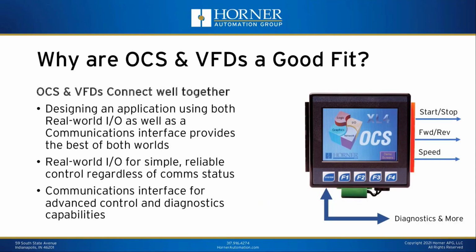So in addition to the I/O connection for basic start, stop, and speed control capability, you've got the ability to add either a full-blown Ethernet or fieldbus-based network connection, or a basic RS-485 Modbus RTU connection, to not only start and stop the drive and adjust speed, but also to get complete diagnostics in terms of fault codes and those sorts of things. Live statistics in terms of torque readings, current readings, and bus voltages are all available through those connections.